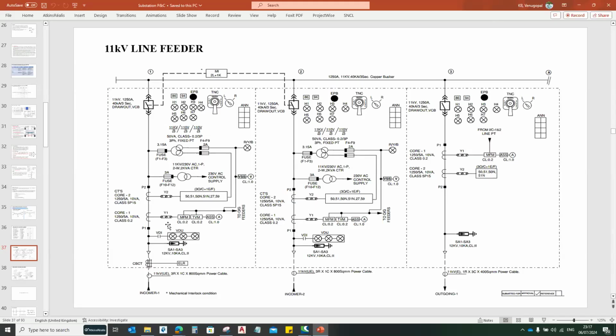Along with this, I am also providing multifunction meters as well as trivector meters. These are very useful to measure the total energy imported or exported to the user from the grid. Based on the energy parameters available in the TVM and the multifunction meter, they will go with the revenue. They calculate the total power utilized by the user, then cost the amount based on how much they used. Similarly, the ammeter provides the indication of current availability in the R phase, Y phase, and B phase.